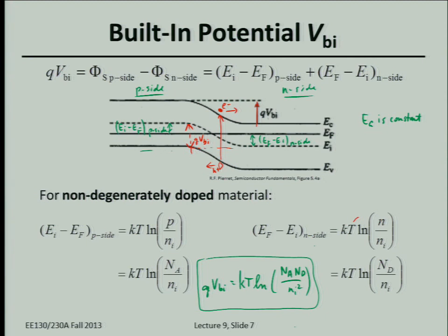Okay, that's one example. For a MOSFET, most of the depletion region is going to be on the more lightly doped side. Actually, that's not good, because if the depletion region of the drain of the transistor reaches across the short channel, the short distance of just tens of nanometers, and touches the source junction, then you basically have what we call punch through. So carriers can easily flow between the source and drain out of control of the gate. So that's actually bad. For a MOSFET, we don't like to have a wide depletion region if we want to make very short channel MOSFETs. So depending on the application, you want either a wide depletion region or a narrow depletion region.